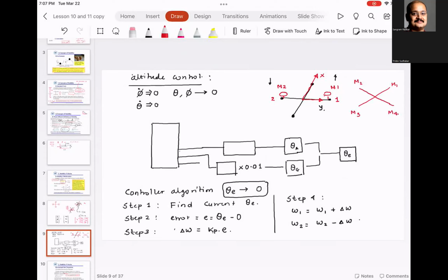So what you will do is you will increase. Can someone tell me the algorithm real quick? My north is down, like this. This is my Y, this is my X. So if I want X stabilization, the motor speeds M1 and M4 should increase, and M2 and M3 should decrease. Are you with me so far? That is how you would do it. Now I'm going to take you to MATLAB and show you where it can be done.